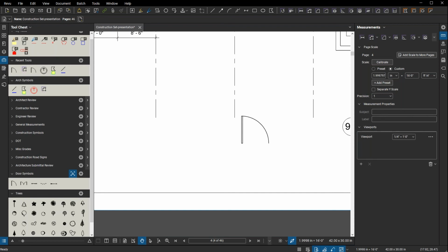Now, what I would highly recommend is that you don't have symbols in this one tool set that come from different scale sources. Meaning that I don't want to have, well, this door is meant for a 1/4 scale, but that door is meant for 1/8, and then this window or door is meant for a 1/16. You're setting one baseline scale. So all the symbols inside of there should come from that same size base scale. So if they all came from 1/4, then they should all have come from that same 1/4 inch plane. That'll give you a much more consistent result to how those get applied to the PDF that you're trying to assign them to.